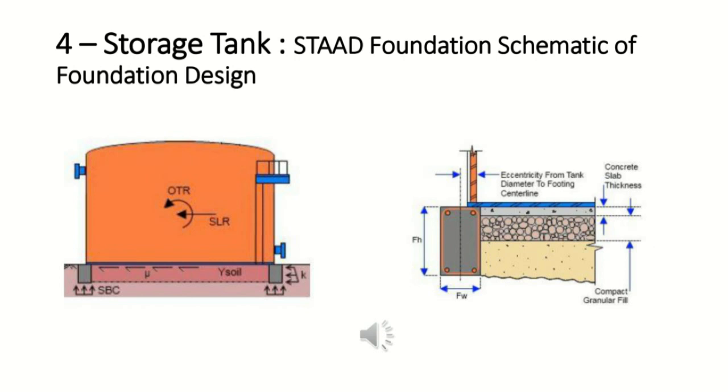Also, it gives you the thickness of compacted granular fill. So this thickness will have to be specified in the application, because from there you'll be able to calculate, based on the soil bearing capacity of the location, including these materials that have been added and compacted, whether it sufficiently supports the storage tank.